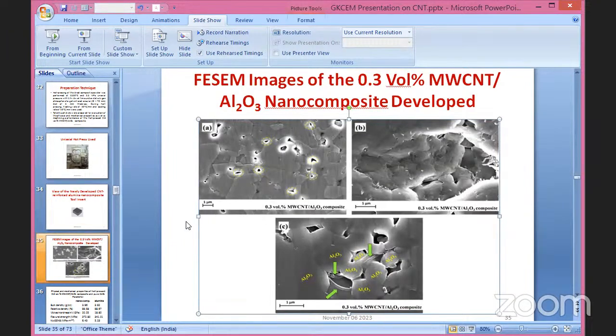They are actually the multi-walled carbon nanotubes, small threads of short length. In Bengali: they look like small threads, visible here and there, sticking in the gaps. But this small amount of multi-walled carbon nanotube itself gives the excellent properties required to improve alumina as a cutting tool material.